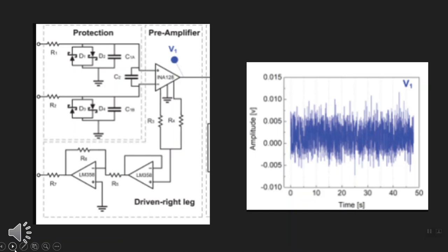At the beginning of the circuit, the instrumentation amplifier is used to reject the majority of common mode signals. It must have a high input impedance in order to minimize signals being lost at the skin electrode contact. This component must have high CMRR, or common mode rejection ratio. This will reject noise from the input of the signal.